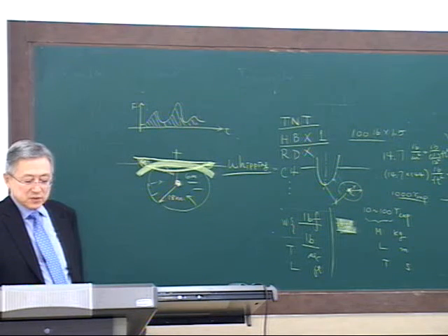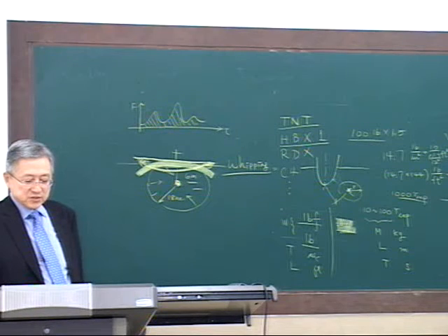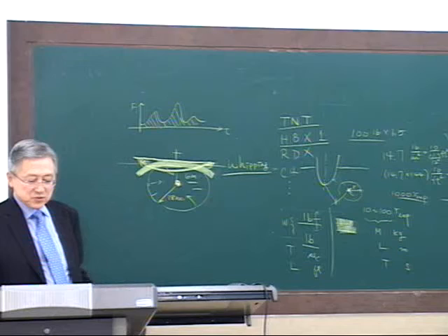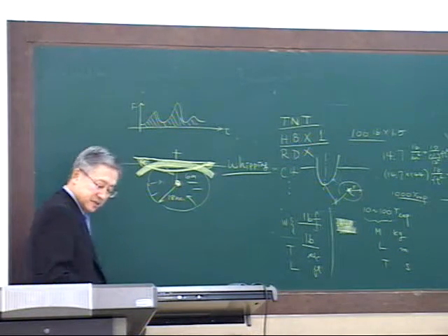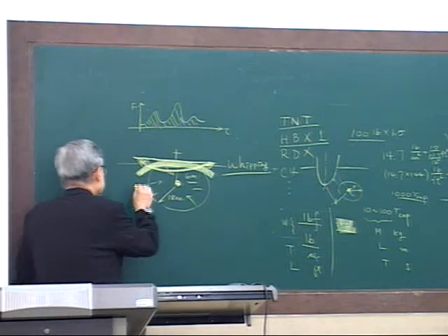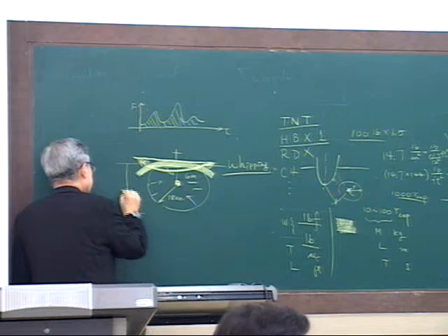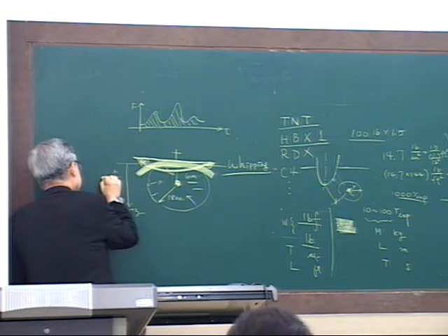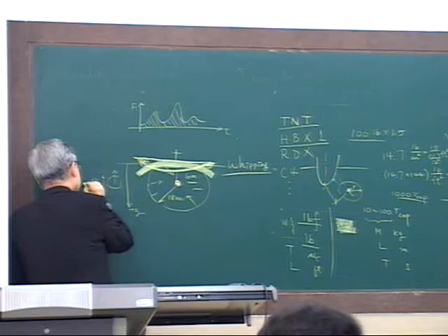Then u is the vertical velocity of the gas bubble. We set z positive as the upward direction. I'm sorry, z is positive going in that direction, so it is plus g. u is the gas bubble motion as it goes up, which is dz over dt.